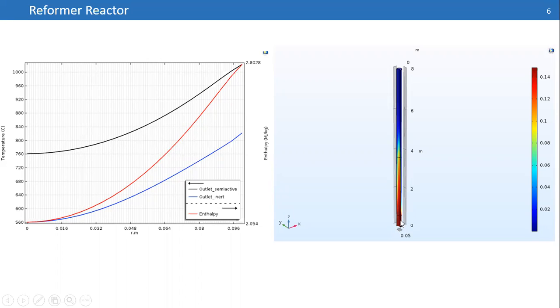we applied just the Brinkman equation to solve the velocity profile inside the bed. And we also added the heat transfer equation to investigate the temperature profile in the bed. And we also solved the mass balance because we wanted to calculate the composition of the different elements.